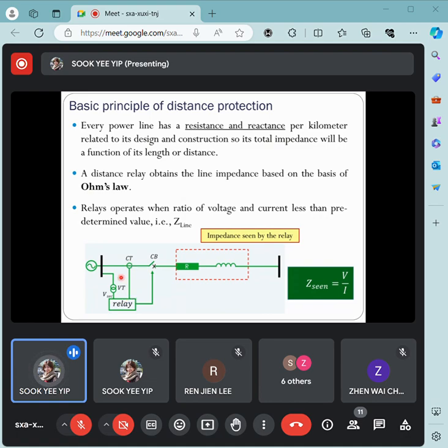All right, so after getting the readings from both the current transformer and voltage transformer, it will divide the voltage and current value to see what the impedance value seen by it right now is. In the event that the total impedance calculated is lesser than the pickup impedance value, usually set at the transmission line impedance, that means it recognizes that a fault occurred. So this distance relay will start to issue the triggering command to the breaker. That's how we isolate the faulty line by using the distance relay.